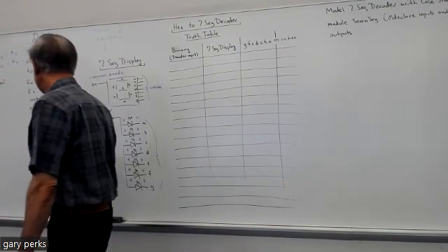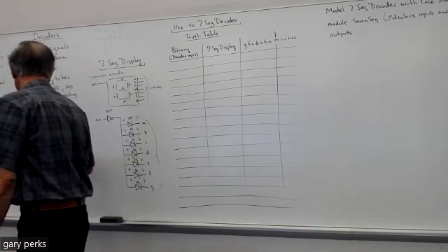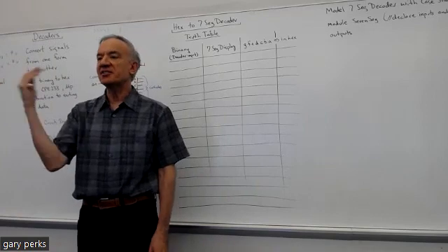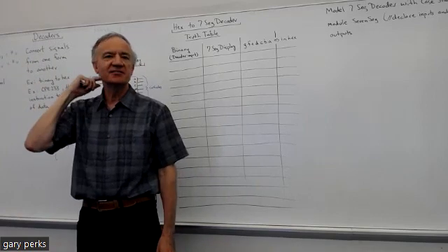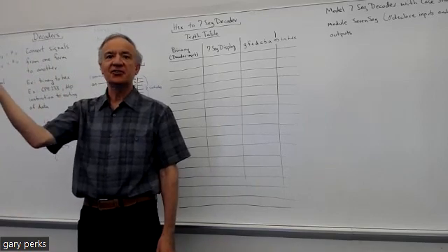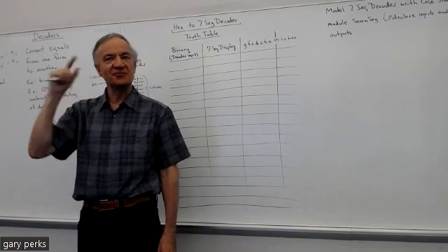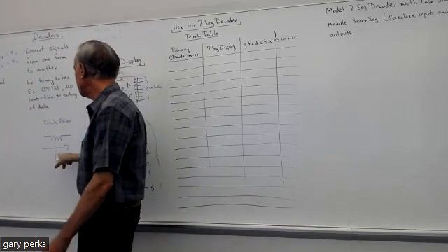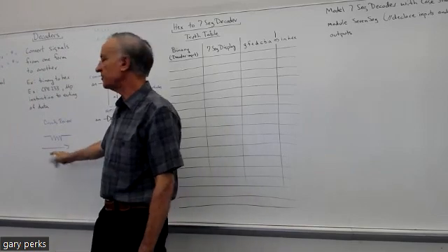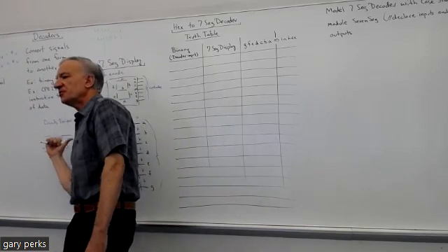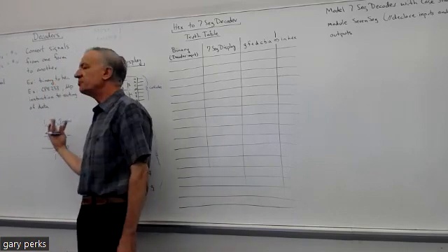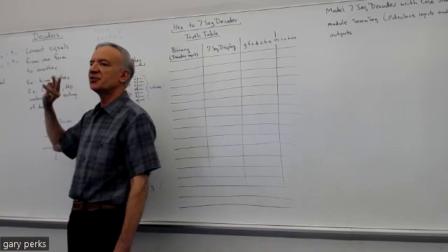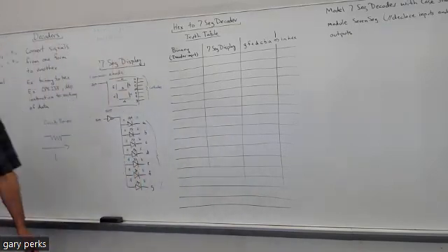Say you have a resistor. And you want the current, now, you know, assume the current is positive charge flow, right? You all learn that in engineering, we think of current as being movement of positive charge, where physicists, you know, they look at the electron flow, but we look at positive charge flow. So if this is positive charge flow, I want the current to flow this way through the resistor. What's the polarity of the voltage going to be? Like, where's the higher end of the voltage going to be, and where's the lower end of the voltage going to be?